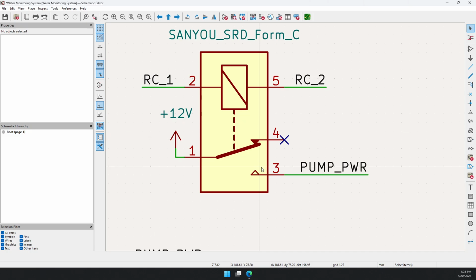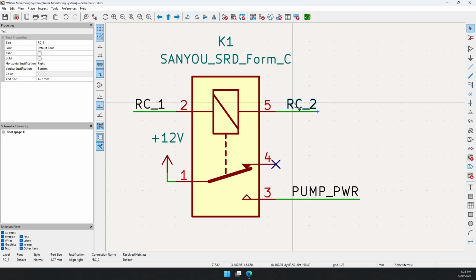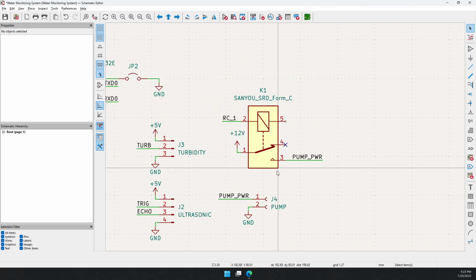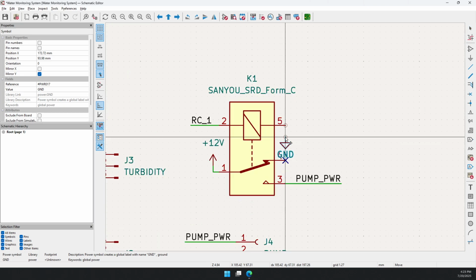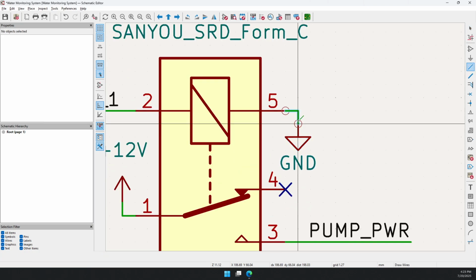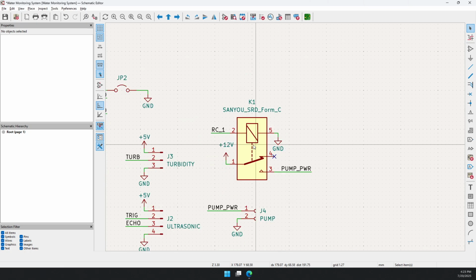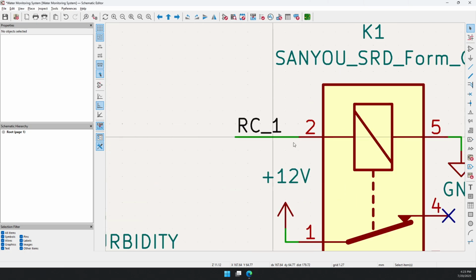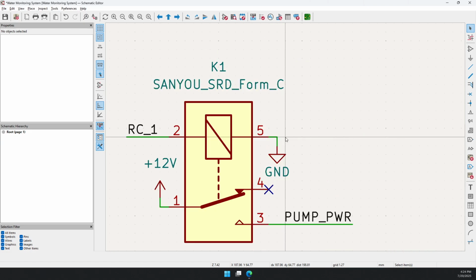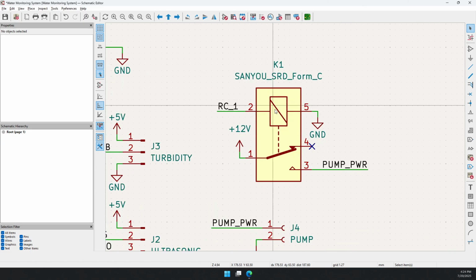All right. And the one mistake I just realized I made. Here should actually be ground. Because all you have to do is supply 5 volts here, and the other side should be ground. All right. To energize the relay. I hope no one is confused. Let me pause once again, and if any question, we will take it. I'll also take a water break.